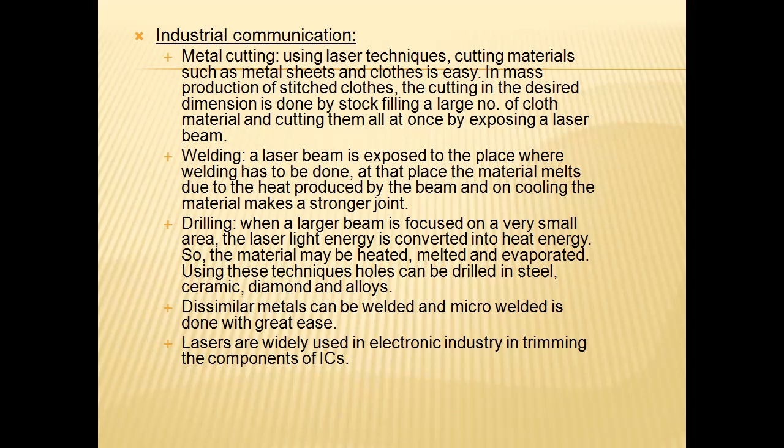Welding means a laser beam is exposed to a place where the welding has to be done. At that place, the material melts down, and due to the heat produced by the beam and on cooling, the material makes a stronger joint. And for drilling, when a large beam of laser is focused on a very small area, the laser light energy is converted into heat energy so that the material can be heated up, melted, and evaporated. Using these techniques, holes can be drilled in steel, ceramic, diamond, and alloys also. Joining two dissimilar metals can be done, and micro welding is done with great ease using lasers.